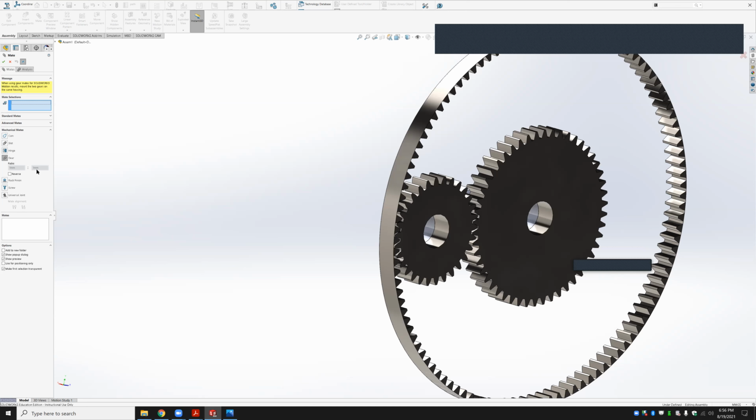The difference there, I don't even remember fully the equations that are going on here mathematically for the analysis side of this. But basically, when you have two external gears meshing, like the sun and the planet gear, you have a change in sign in the direction. So one's going to spin clockwise, the other counterclockwise. But when you have a mesh between an external gear and an internal gear, like the ring gear, where the teeth are on the inside, the gears are going to spin the same way. So that's why you have that reverse option for your gears.